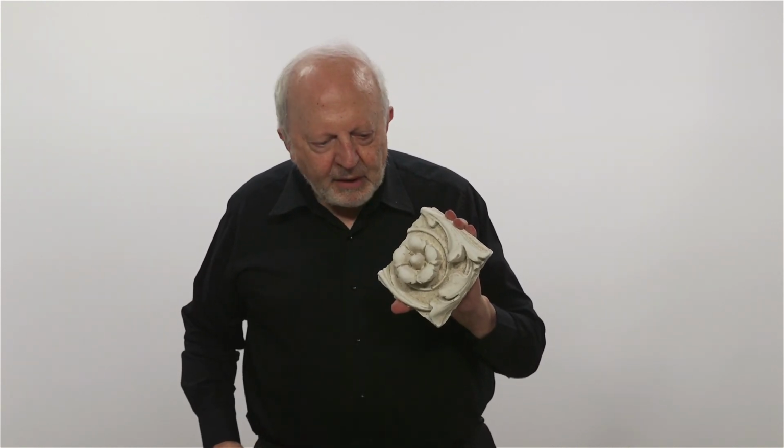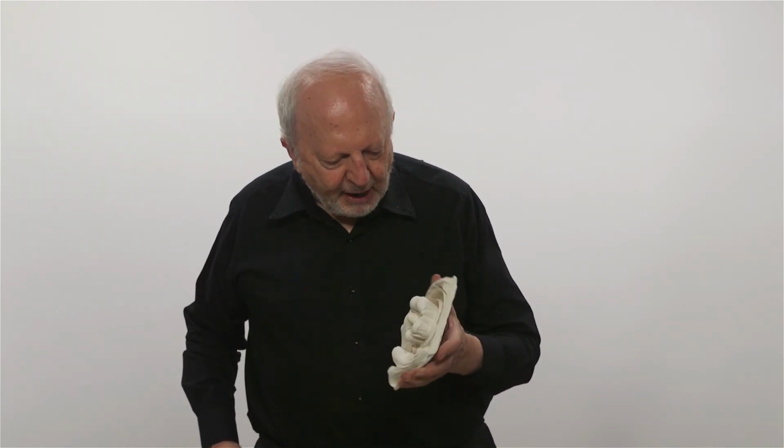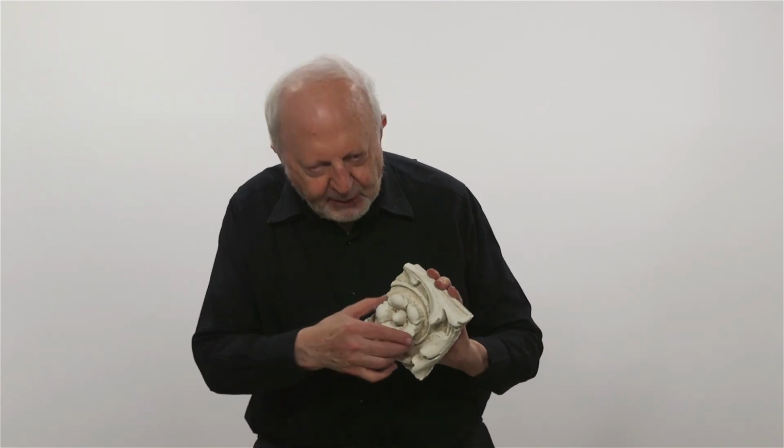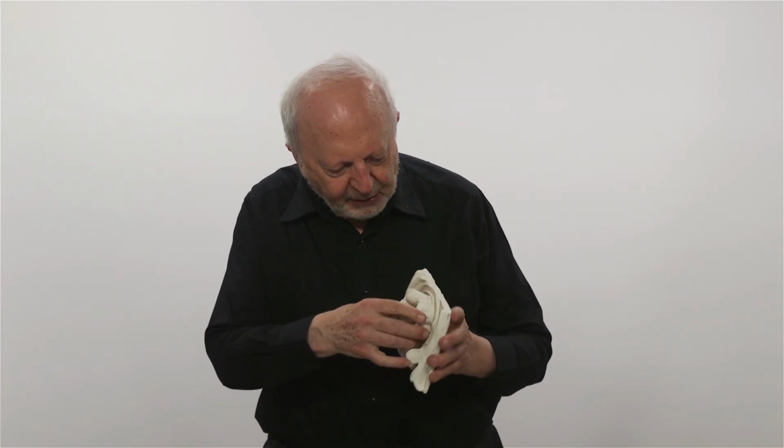And then the same way, for mouldings like this, you may need to again use Keene's cement to get greater strength. These are quite difficult to make, and I can't describe it in detail here. They have undercuts, which means you tend to make them in a silica gel mould, which can then be peeled off to get that complicated shape.